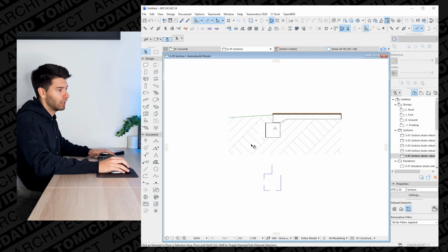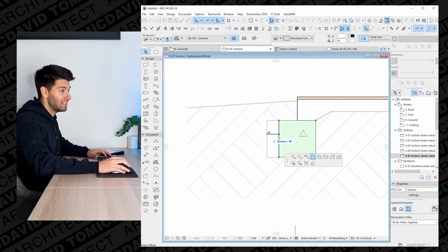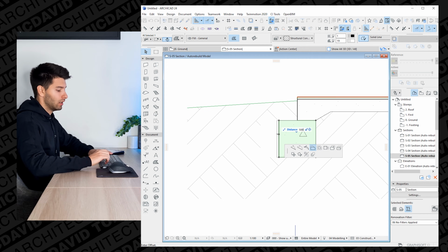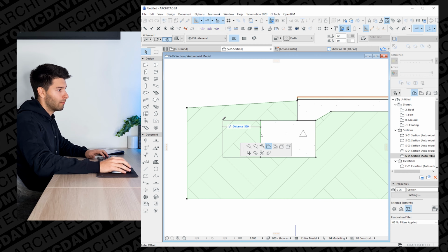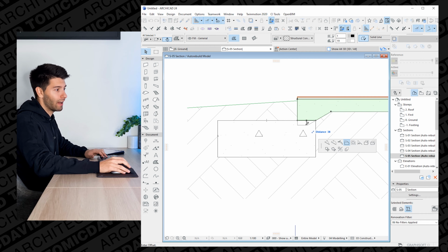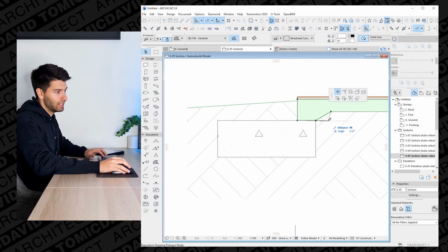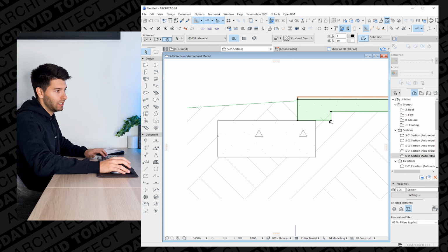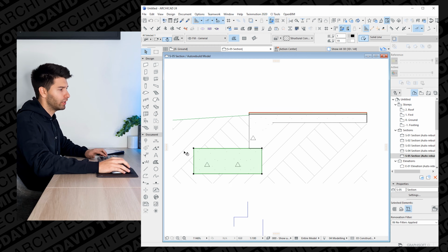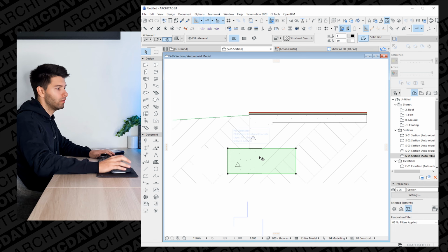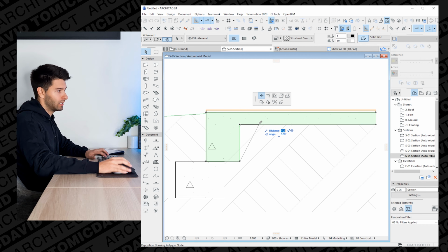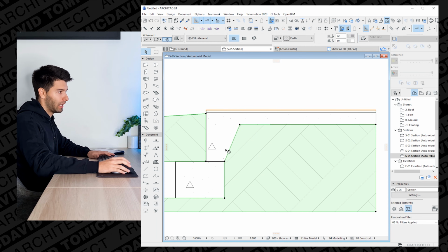I'm going to move the waterproofing membrane just out of the way for now, and I'm going to extend the size of this footing down below. So at the moment it's 300, I'm going to extend that to 800 wide in total, making sure I extend the earth as well so it can be seen. And instead of 172 drop here, I'm going to have a 400 millimeter drop. Now that isn't obviously going to work straight away, so what I'll do is I'll drag that across so it doesn't disappear and push that down 228. Before I finish off moving all my earth hatches, I'm going to move that concrete footing centered 400 millimeters, and then I'm also going to extend that, let's call it 250, so it has an edge thickening.